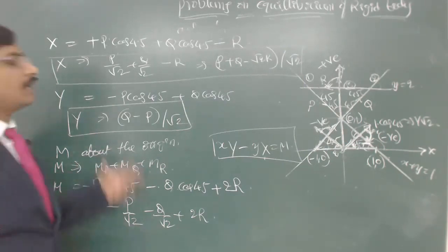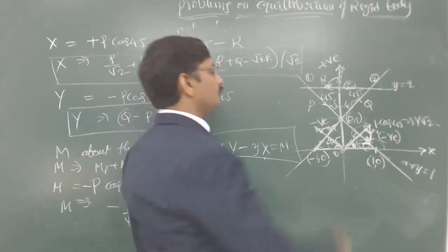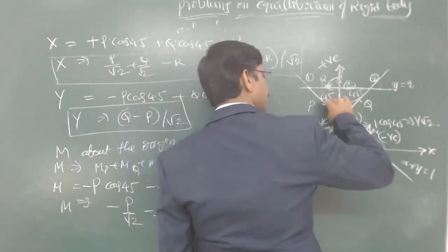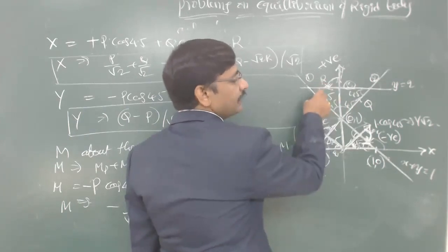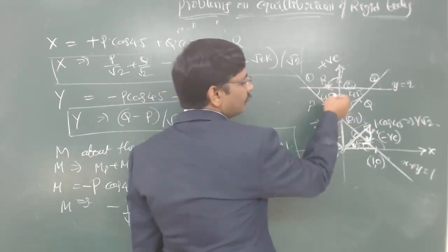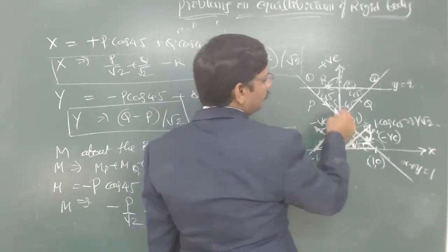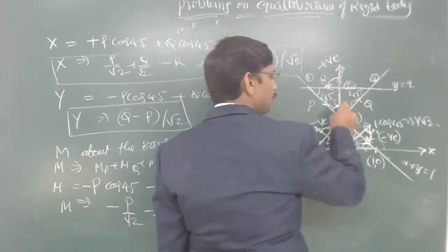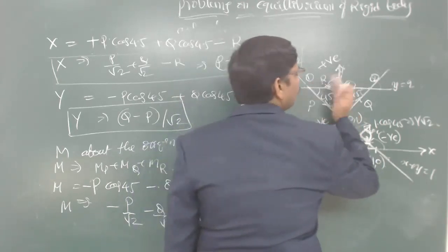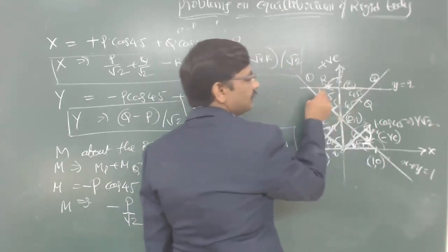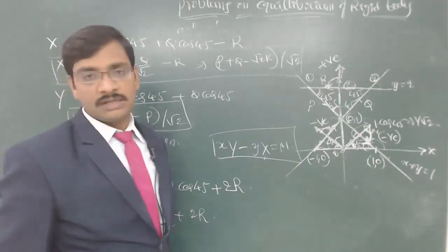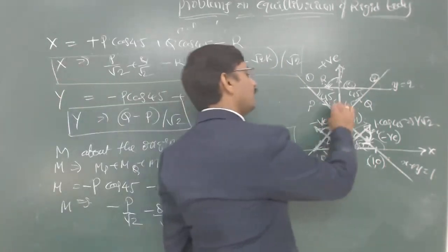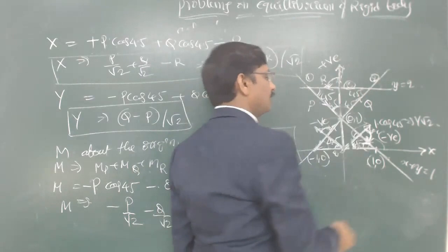So you want me to recalculate the y component. So the y component, this is P direction in the negative y direction, so downward. So this angle is 45 degrees, P into cos 45. Sorry, this angle is also 45 degrees, right? I have taken P into cos 45. Because this is also 45 and this is also 45, it is not making any difference, cos or sine. So this is 45 degrees, P into cos 45 in the negative direction.